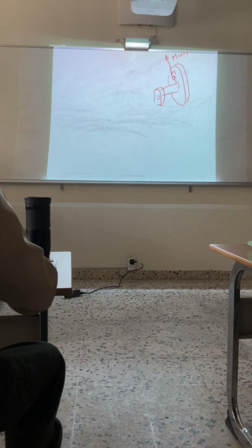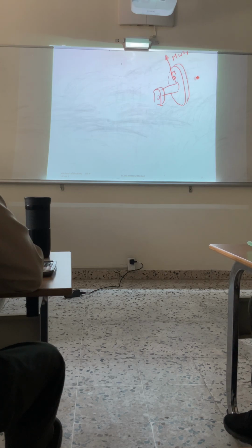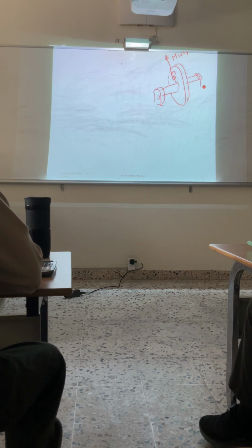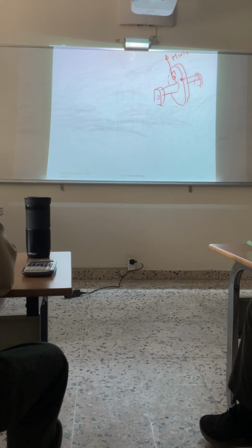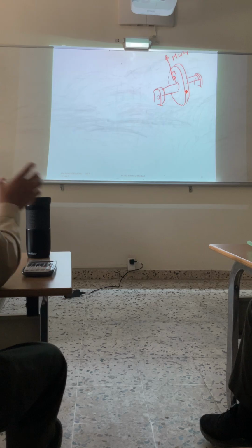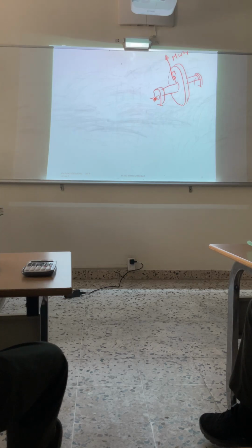Actually, it's a very huge structure. It's not allowed for you to make any mess inside the casing. So you end up adding the two dummy discs on the right and the left. Okay, and in these 2 dummy discs you add up your balancing masses. So I'm assuming that this is the case of the turbine, and these are the 2 bearings. You may add up the 2 discs on the same side or 2 opposite sides between the running disc and the bearing, or outside the bearing. So let's deal with this case.